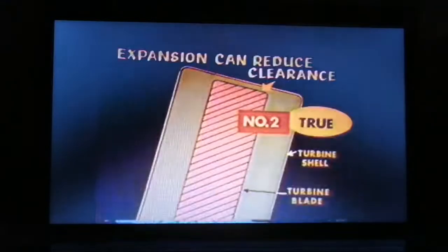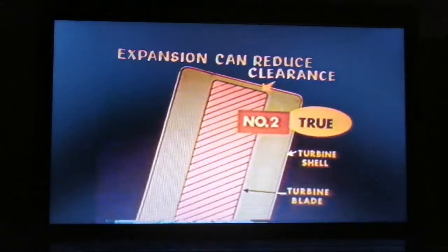If you answered question number 1 false, you were correct. Critical speeds when turbine vibrations are strongest are speeds to be avoided. Number 2 is true. Uneven heating of the heavy metal part in the turbine can be caused both by starting or stopping the unit too rapidly.